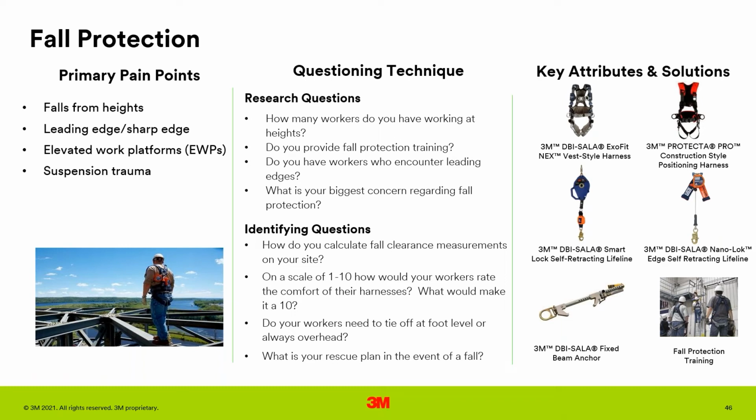So the way that we've engineered this arrest mechanism, it can better accommodate a worker's natural work motions, and it's reduced lockups by about 29% in those horizontal applications. And then in vertical applications, this SRL helps protect workers up to 310 pounds from falls when working with a 4-foot fall clearance, meeting OSHA's 1910 general industry rule.